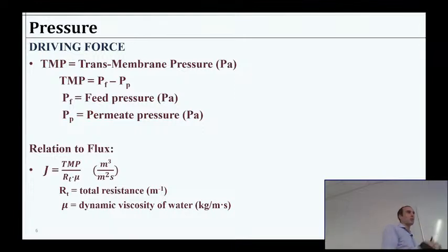So unless you were going to take your apparatus to Mars, where you have a bigger differential between your atmospheric pressure and your vacuum, you're only going to get so much pressure by doing a vacuum-driven membrane. Now, for some cases, that's plenty, right? For some membranes, some operations, a vacuum is a perfectly reasonable way to pressurize your membrane. In other cases, you just have to go higher, and you would have to drive the water at the membrane, pressurizing the water itself.